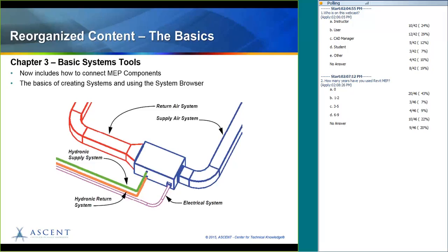So in here, because you need more linear elements to do this, we have align, trim and extend, split, and offset. Align you can use with anything, but some of the others, it really is specifically for the linear elements like the pipe and duct and cable tray.